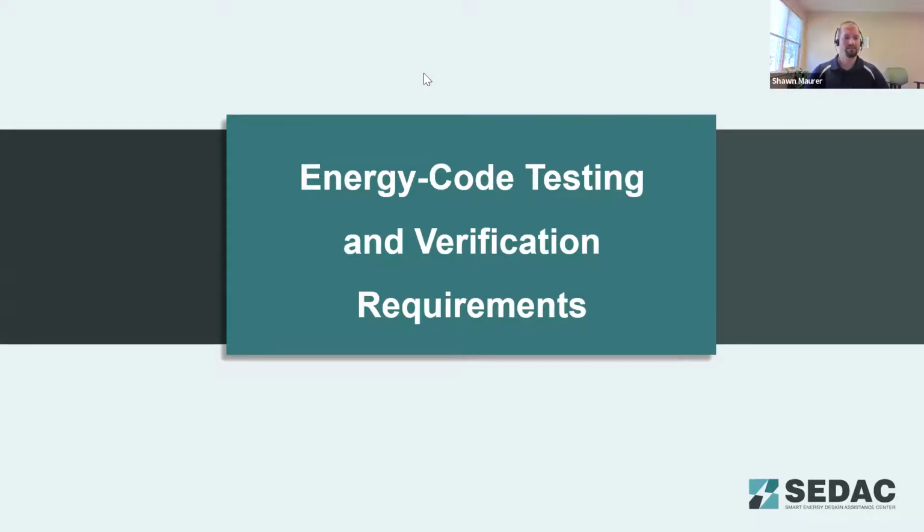And for our second answer, it looks like most people got this one correct as well. Commercial only requires high pressure ducts, that 3 inches of static pressure or greater design pressure, must be tested. Duct leakage is only optional for residential if it's all inside the conditioned envelope. If you have any ductwork in the attic or a crawl space, then that ductwork needs to be pressure tested.